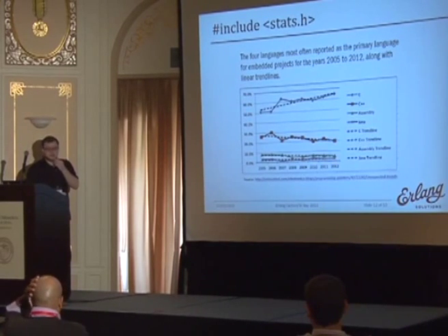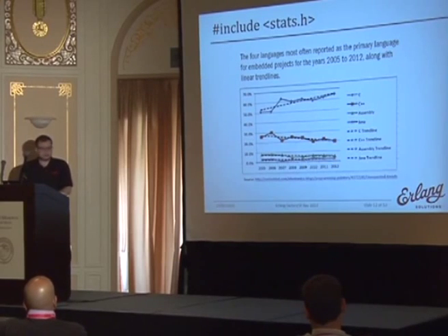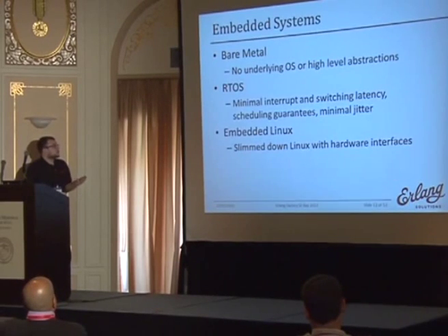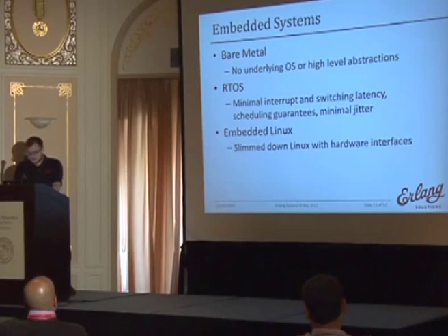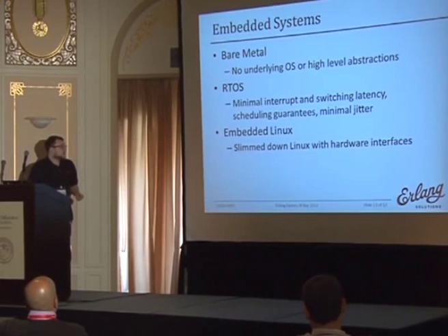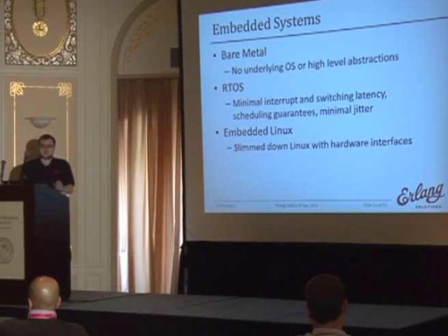So how we actually architect these embedded devices, what are the methodologies that we use? So 3 approaches. You can either do bare metal programming. It means that there is no operating system. You just write really low-level code, write your own handcrafted interrupt service routines, etc. This is not very realistic for a moderate complexity device, because you need to write a lot of very fine-tuned, very low-level code, and generally this is only viable if you are producing something extremely specific or niche, and you need the speed. By ditching the operating system, you get extra speed, obviously.